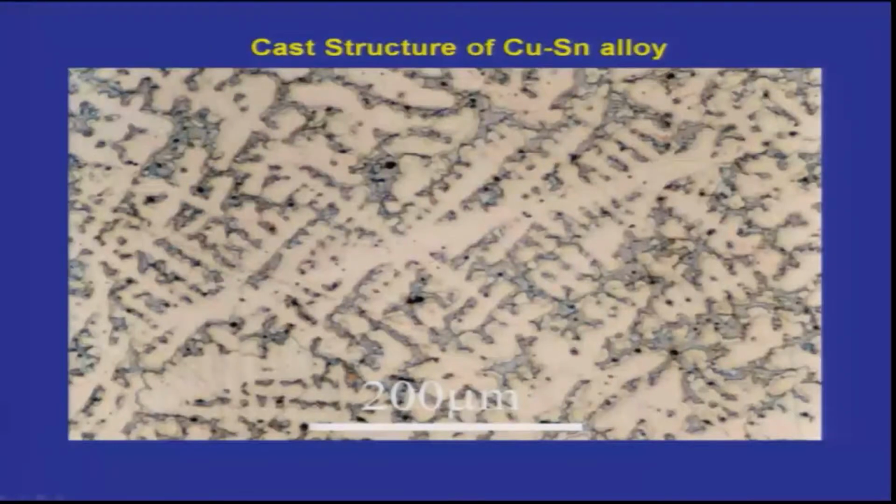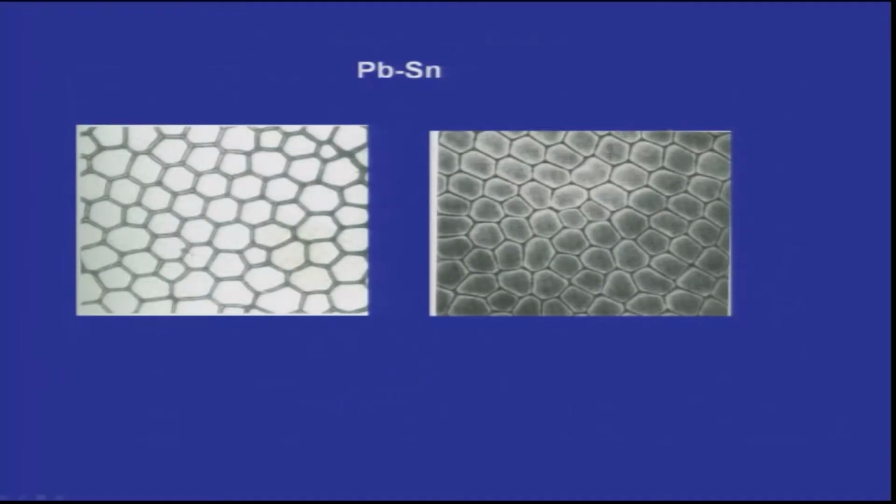This one is copper tin, which is a bronze, and as you see here these are the dendritic structures which are revealed. There is some other phase, beta, present as the yellowish colored phase, and the dendritic phase you can make out in some of these places, where you can see the dendritic structure develop. Everywhere, and in between the two dendritic arms, something else has formed, that is why it is a little bit cumbersome to observe, but you can make it out this way. That is what a dendrite is.